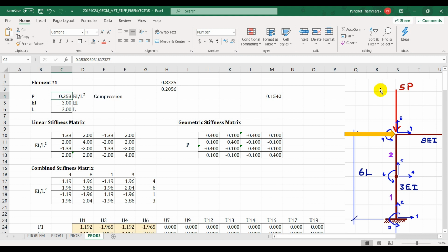Basically, if you plot the load versus the displacement, you will expect what? The slope, what is it? It is pretty much like a stiffness. One axis is the load, one axis is the displacement. So the slope is the load divided by the displacement. It gives you the sense of stiffness. But if you have a linear elastic structure, or you don't have much effect from the second order effect, second order moment, you will expect more or less a straight line.